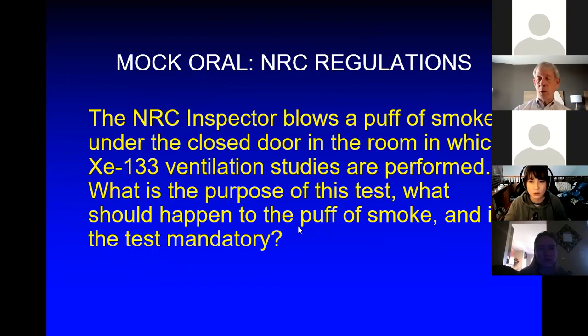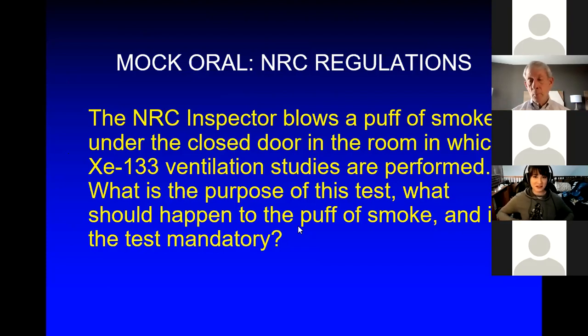Okay, what's the requirement? What's the pressure requirement? Negative pressure. Less than the hallway. Yeah, correct, exactly. So negative pressure means that the pressure in the room is lower than what's in the hallway. And the reason it would be lower is that every room has a ventilation system, which is constantly exchanging the air.